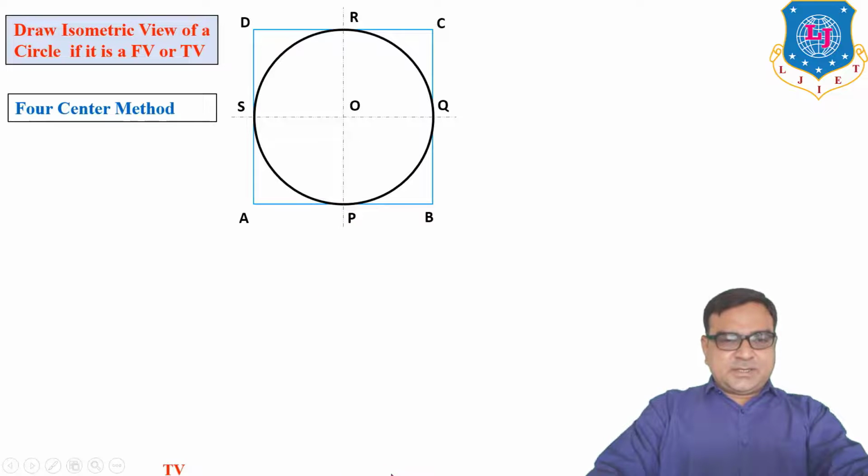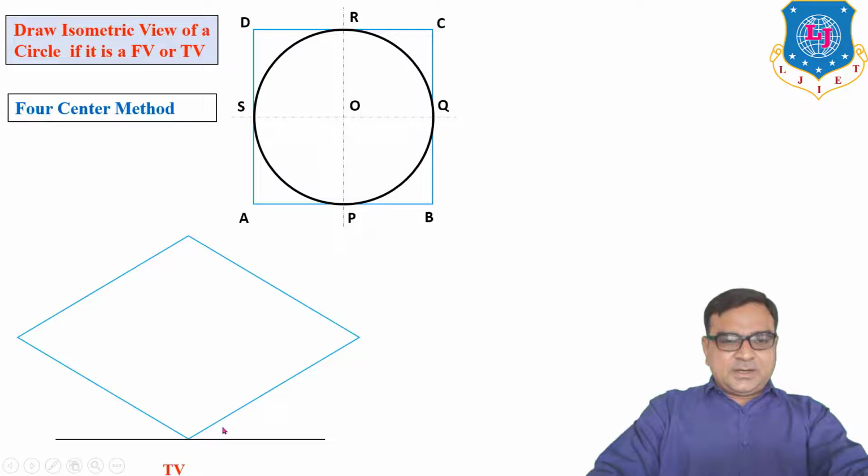First we have to take the isometric view or isometric drawing for the top. Suppose this is the top view. It looks 3D. So first of all draw a horizontal line and from any point take 30° anti-clockwise and 30° clockwise. Draw a line equal to AB. This is BC, CD and DA. Now this square becomes a rhombus in isometric drawing.